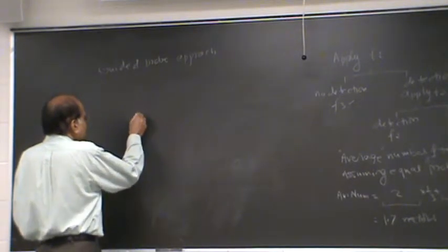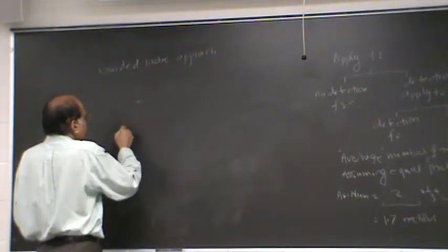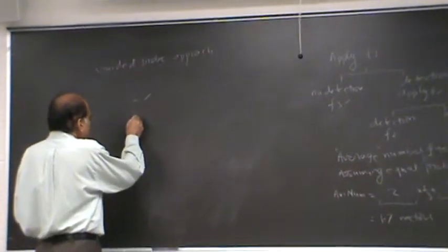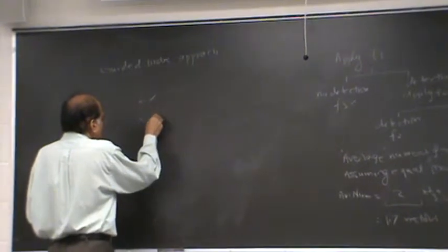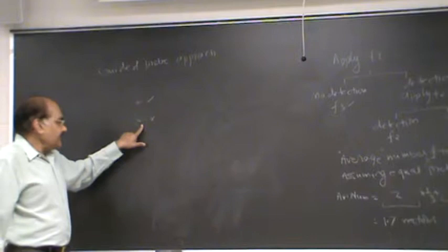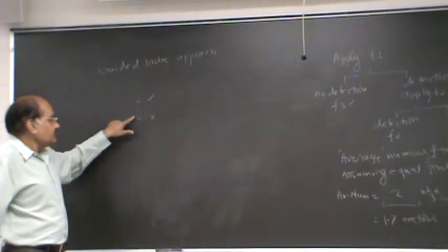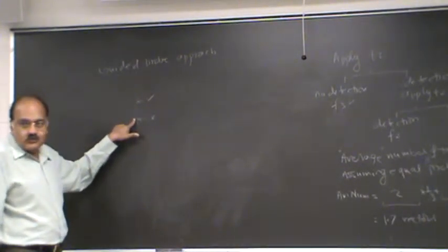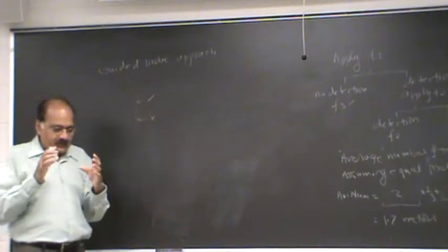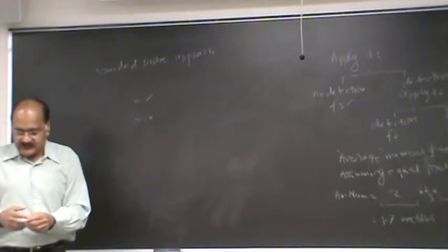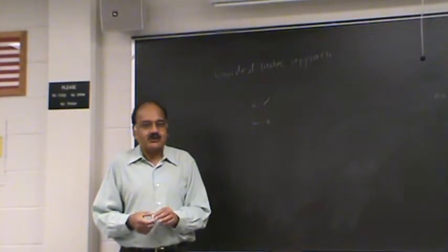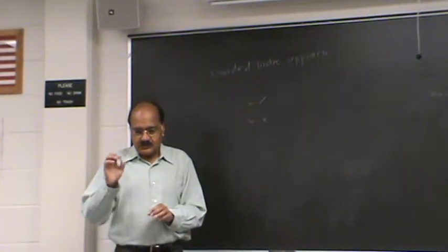so you can trace maybe the error, and you find that here, at this point, things seem to be working okay. And later, you find that at this point, there seems to be some error. And then you will conclude that there is somewhere between here and here that something is going wrong. And in hardware, sometimes it is allowed. You have a board, and sometimes you have a probe, and you probe these chips, and you can possibly identify which particular chip it is.